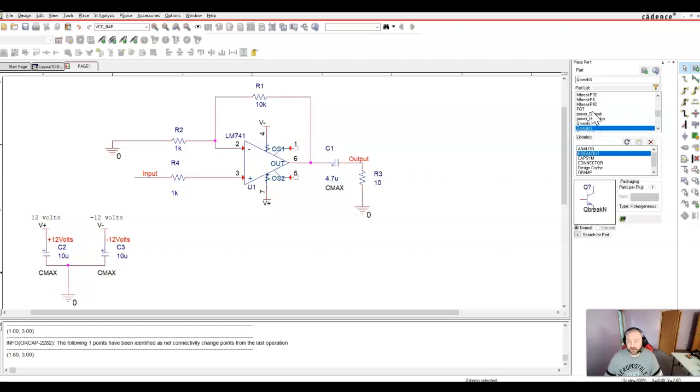These don't necessarily have SPICE models associated with them, but you can see, here's some for transformers and stuff, so there's different ones you can use in the breakout as well. The other thing you can use, I think, is header, like header 4, which looks a little bit different than connector 4, but it doesn't really matter. So in this case, let's just do the connector, connector 4, CON 4.